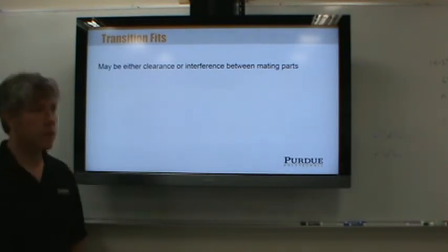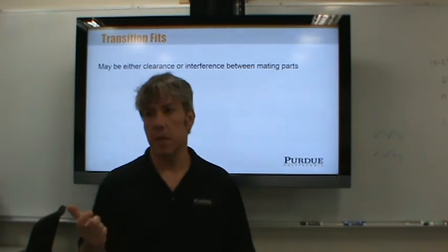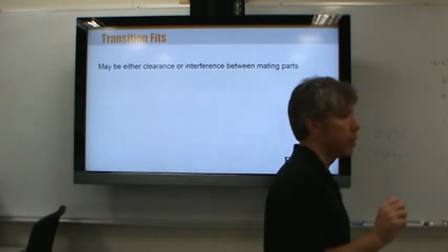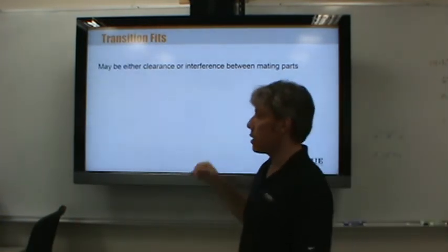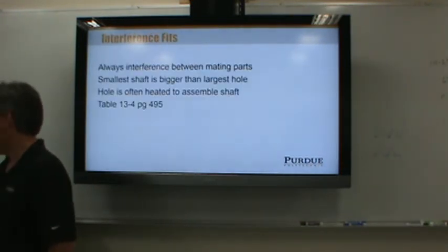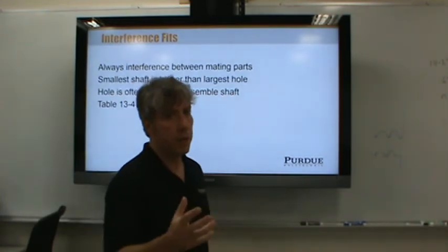Okay, transition fits are fits where there may be clearance and there may be interference. It's possible that the shaft will be larger than the smallest hole. Okay? So this is a tighter fit where you need more precision. In fact, one place where transition fits are used is in cylinder heads.